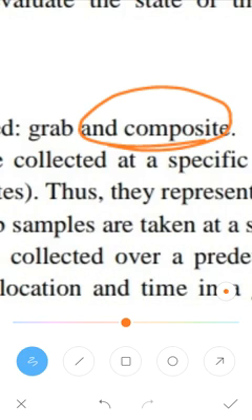For characteristics that are subject to significant and unavoidable changes during storage, analyzing individual samples is preferable, at the sampling point. Examples are dissolved gases, residual chlorine, soluble sulfide, temperature and pH.